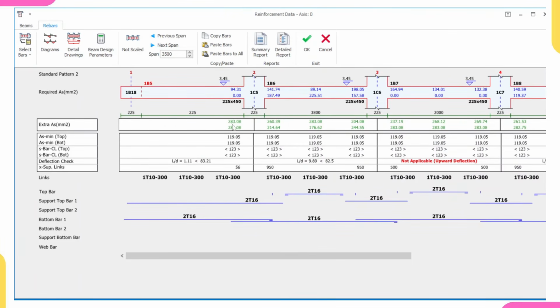So make sure that your area of steel provided is not less than 100 millimeter square. Reason is, but anyway, it depends on your country. If you are in the United States, the UK, Canada, where you are sure that they don't tamper with standard or quality, yes, you can go with what the software gives you. But if you are in a country like Nigeria or other African countries, make sure that it's not less than 100, because you know that in Nigeria, Y16 is no longer Y16. In these African countries, Y16 might just be Y14 or even Y13.